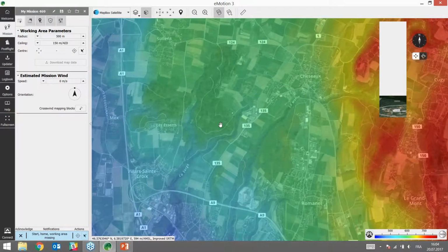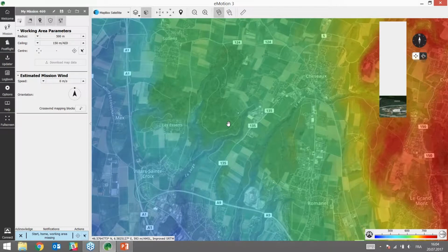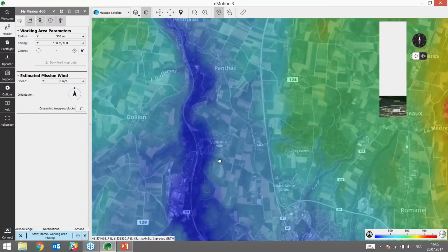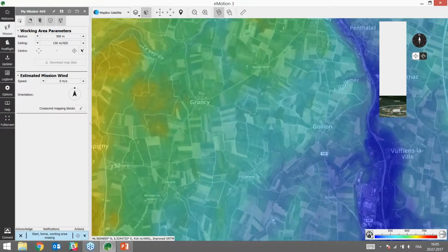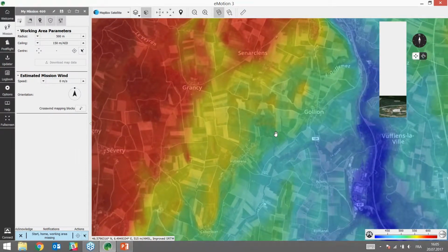When you select it, you can see that now your background map is covered by another layer, a layer that is representing the elevation of the extent of your screen. You can see that there is a color scale with a legend in the bottom right-hand corner here under my mouse. And when you move somewhere else, you can easily auto-adjust the elevation color scale by clicking on this button. I just click and I get a new elevation color scale for a better display.